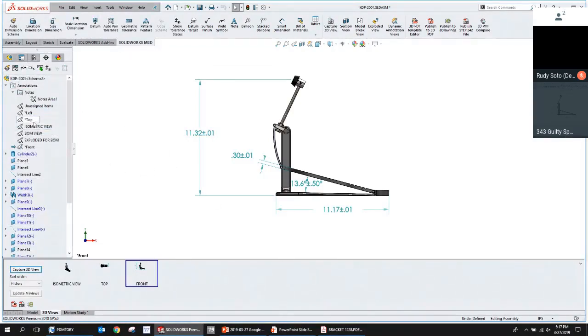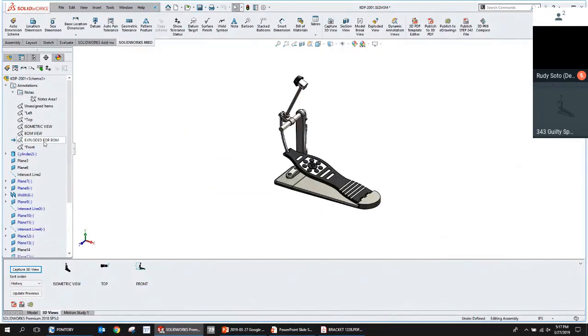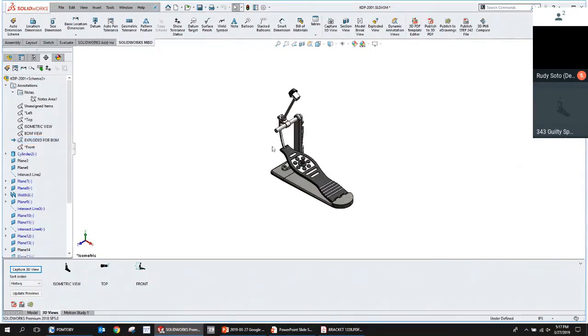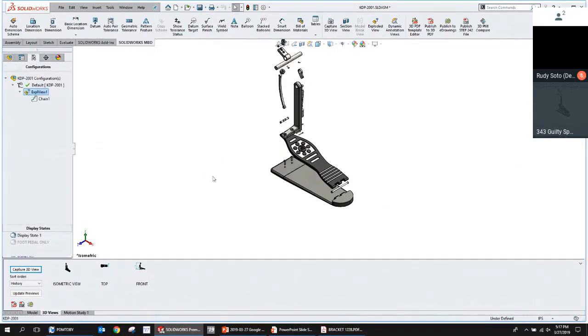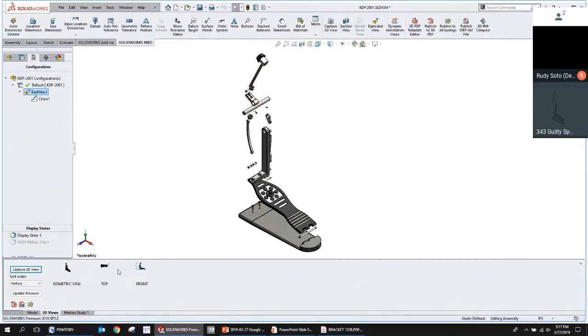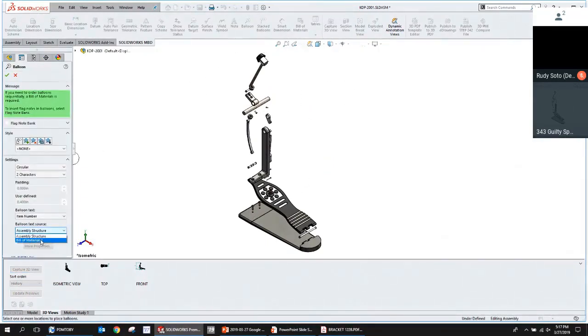And then we're going to go to our exploded view. And we'll just do an orient, so it goes isometric, and we'll take this explode view here, and we'll say, maybe we should throw some balloons on here. So balloon, I'll say I want this to be hooked to that bill of materials that I created earlier, and then just throw some balloons on some of these parts.